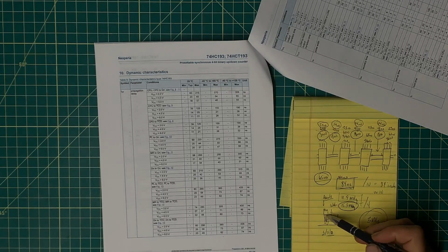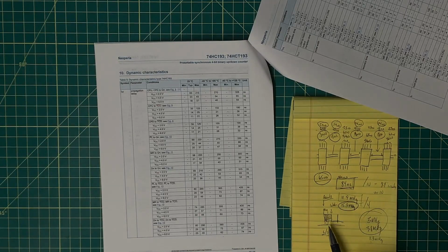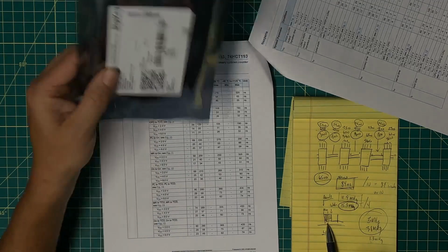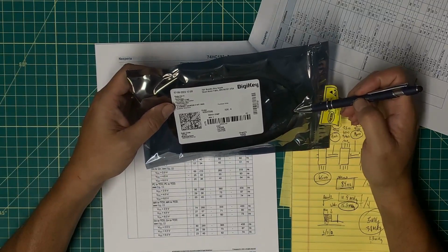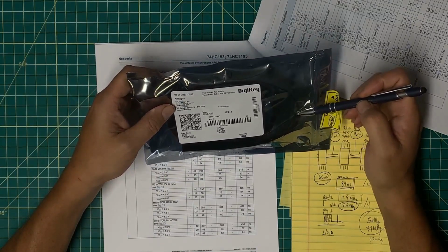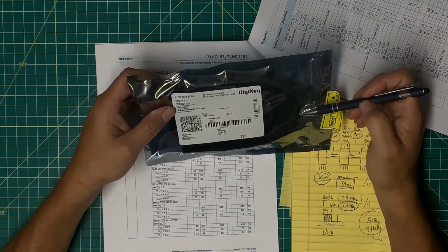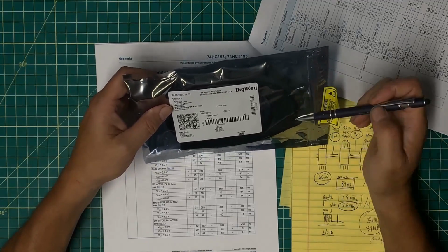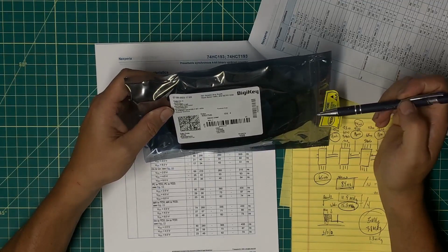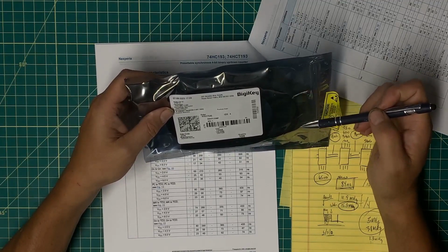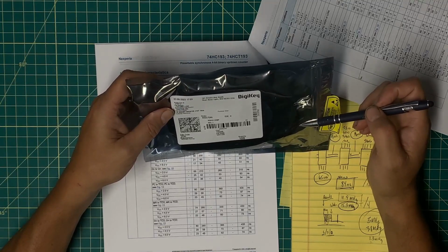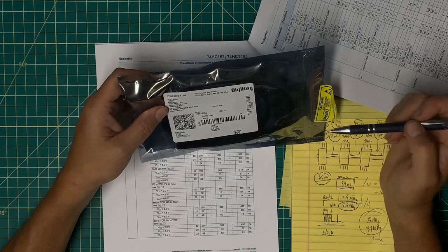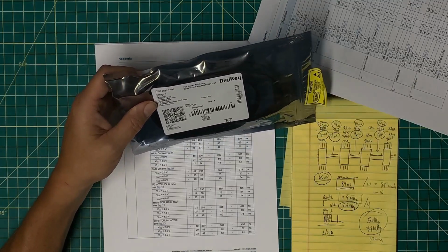So this is going to require a change to the control logic to implement, and I'm not exactly sure what I'm going to have to do with that. This is going to require me to desolder several of the existing ICs and replace them with these. And I want to start with the program counter first to make sure that I can whittle down that timing gap a little bit. I am not going to go all the way there with doing everything all at once because I am a fan of doing incremental changes. That way, if something goes south on me, it's only the last change I need to worry about correcting.